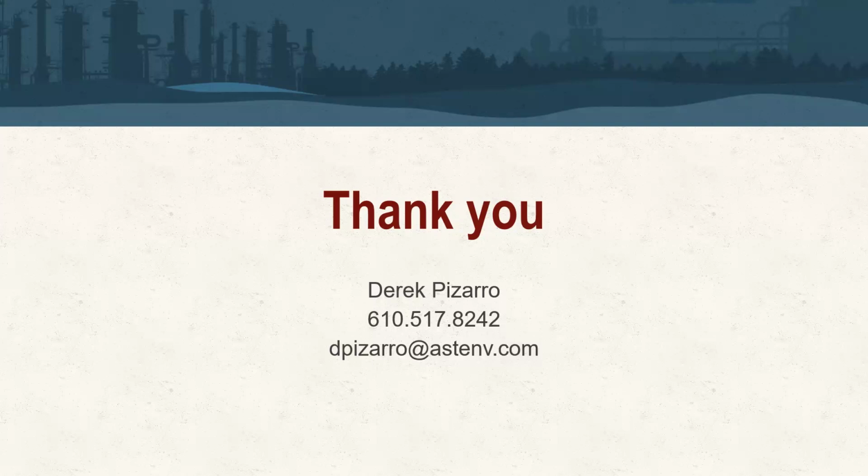And so for me, the majority of the projects I work on, that you work on, Mike, we're doing source zone treatment, we're doing PRB or PRTZ installs. I like a product that I put where I know I need it, and I know it's going to be there after I stop injecting it. It's not going to migrate with groundwater. So there's nothing specifically wrong with some of those other products out there, but from a cost optimization, a treatment efficiency optimization, and a persistence standpoint, I find that we're being asked to use, or we're recommending, iron sulfide a lot more than the other products these days.